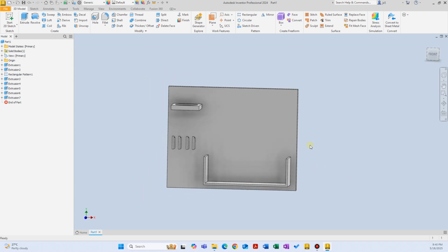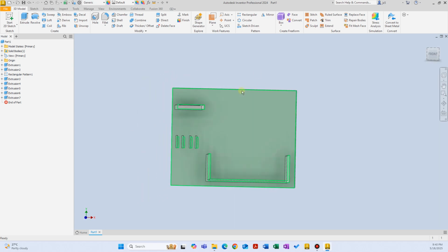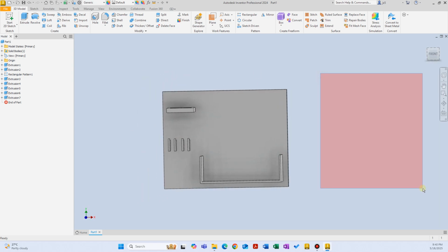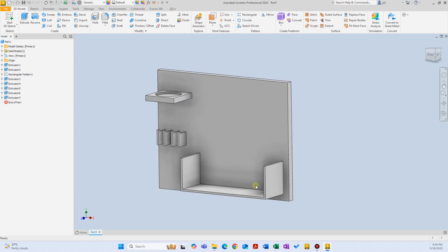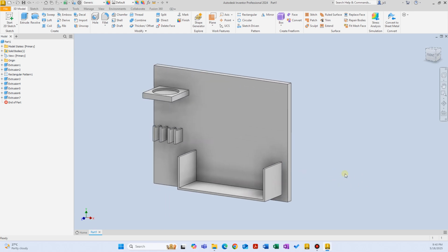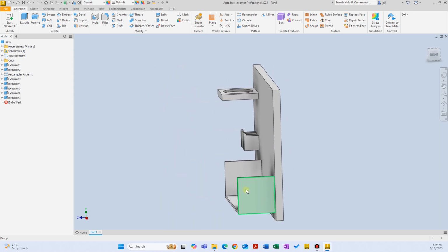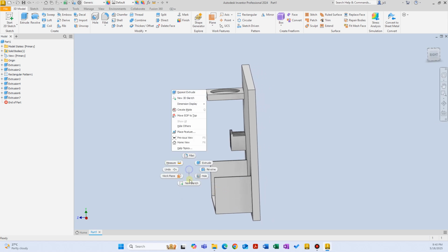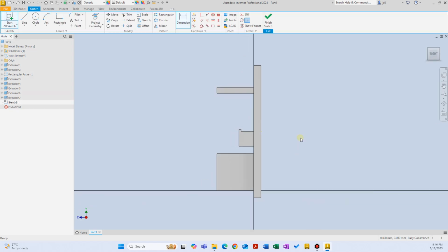Also, in the space where I'm going to install this on the wall, on the right hand side, I have this outlet, which I will use to charge the device here. So I want to be able to feed the charger cable through a port here. So let's just have a quick cutout here, maybe like a little hole or a rectangle. So let's just create a new sketch on this face this time. Right click and project that geometry.